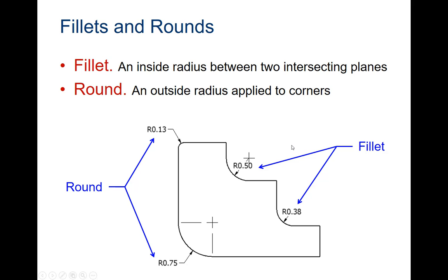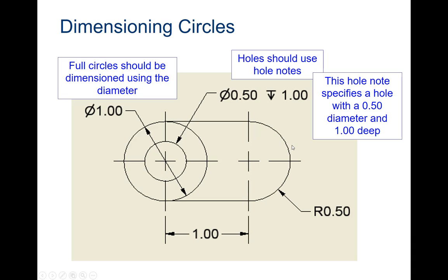Now, when we are dimensioning full circles, you must put in center marks. And remember, there's an annotation feature on the drawing file that allows you to do that. You just choose it and hover near the center. It turns green, and you click it.